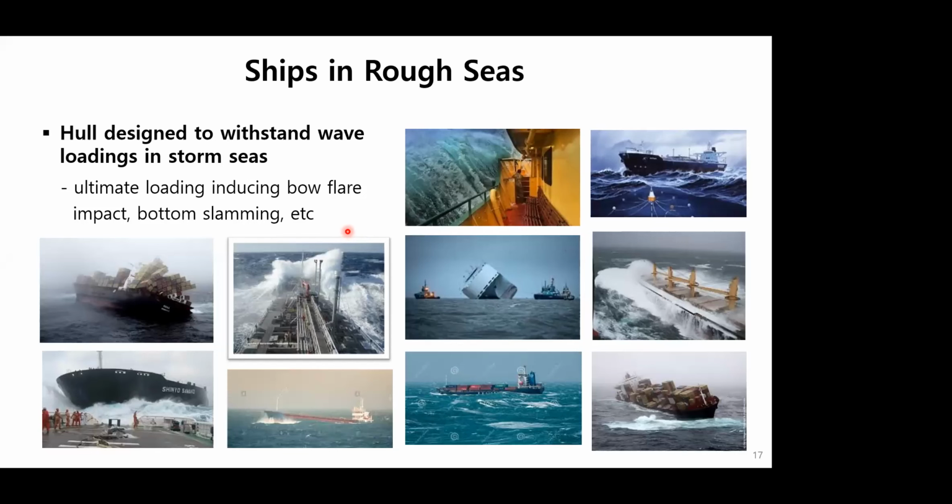Of course, most of the time during the voyage, sea states are not so severe. However, we believe we cannot evade the ultimate loading, but eventually we have to meet such severe loadings. So we need to design the hull against those severest loadings. So hull designers always think about which is the most critical condition.